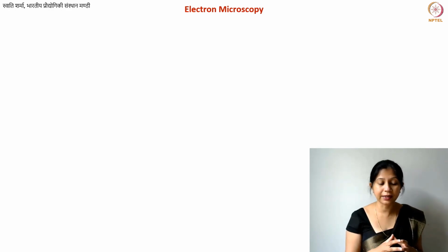One important thing, and I will probably tell you this again in this lecture, is that TEM should not be your only analytical tool. Whenever you've made a carbon material, even if you know what material you're making, whether it is nanotubes or graphene sheets or a bulk carbon, in all cases, TEM should be more like a supporting technique, and that should not be the only technique. X-ray diffraction often gives you a good average of the crystal structure of the entire material. In the case of transmission electron microscopy, you're often looking at a very small region. And there also, the interpretation is not all that straightforward. This is what we are going to discuss.